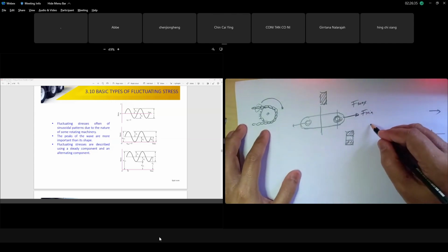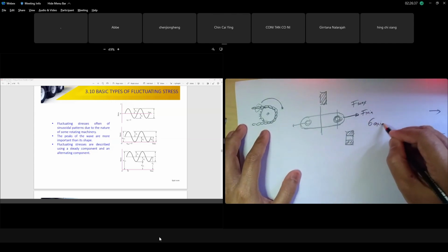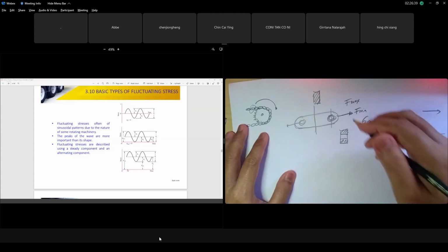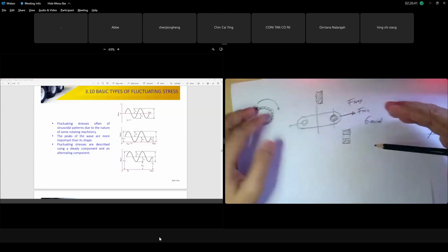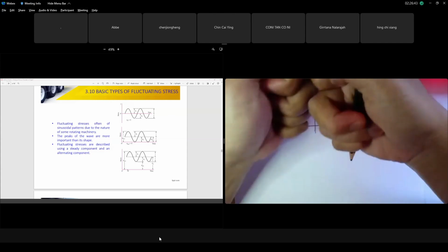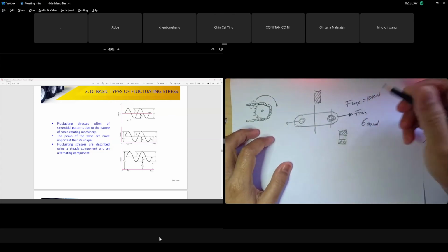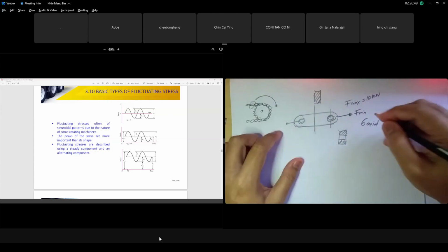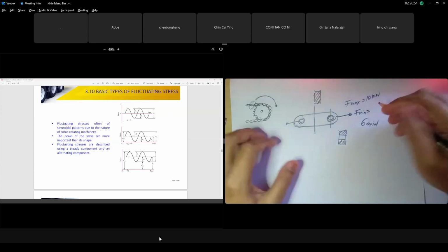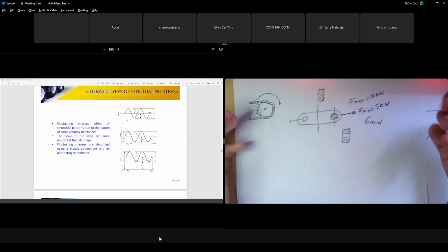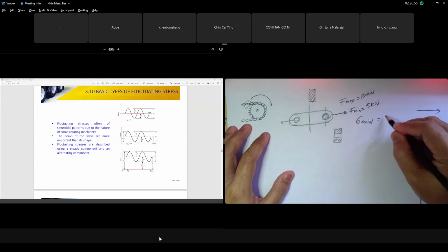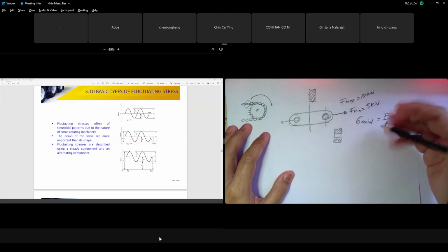Okay, F maximum, you got sigma. You know what is your sigma axial, right? Sigma axial is because this is all axial stress. When it's full pedal, the tension on the chain, we have F maximum, 10 kilonewton. For example, when it's not full pedal, the minimum force pulling the chain is 5 kilonewton. This is an example. So sigma axial is force over area, right?